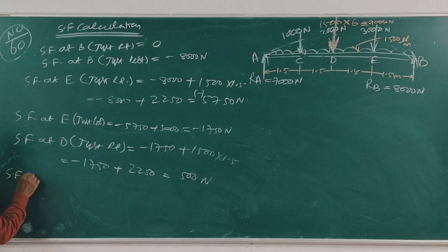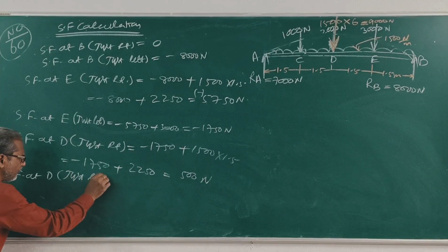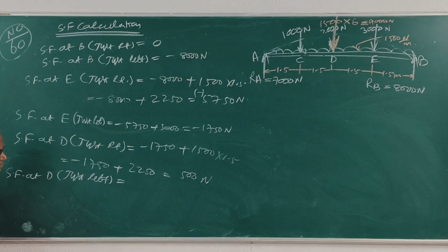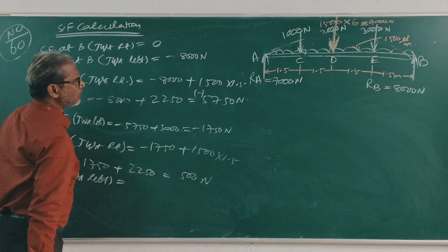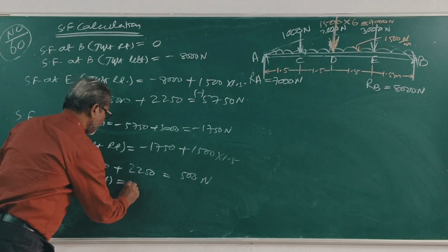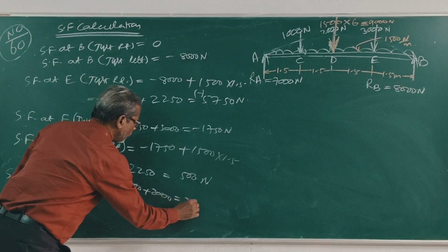Shear force at D just left is 500 plus 2000, which is 2500 Newton.